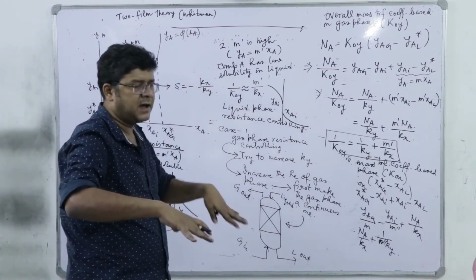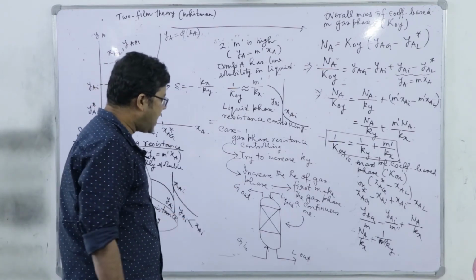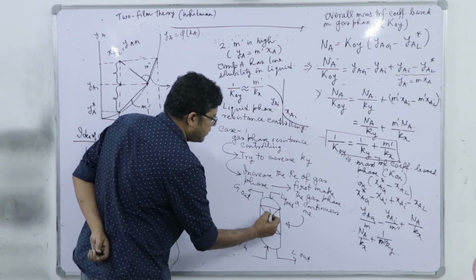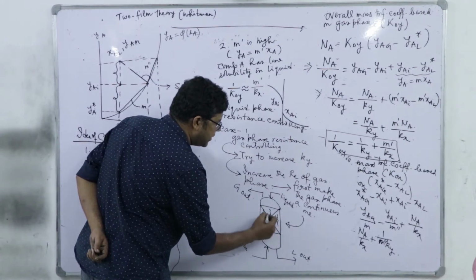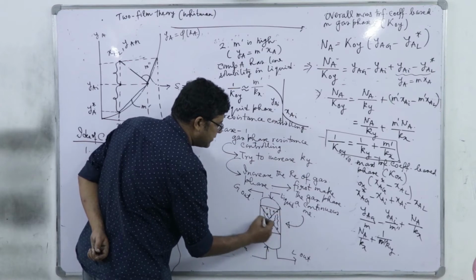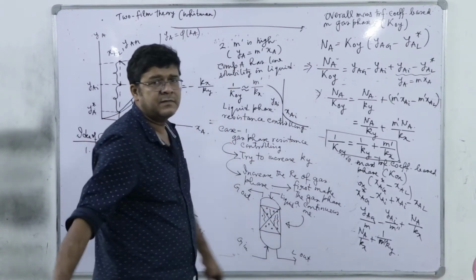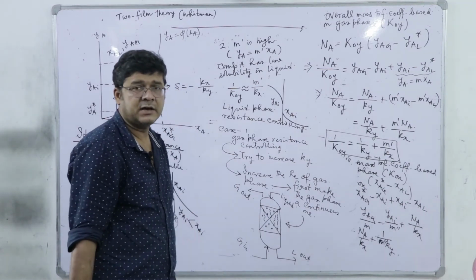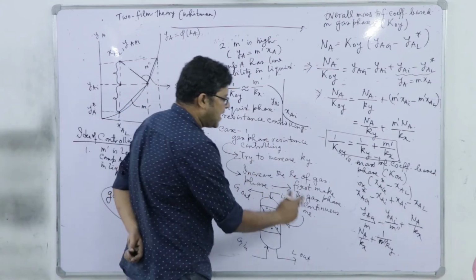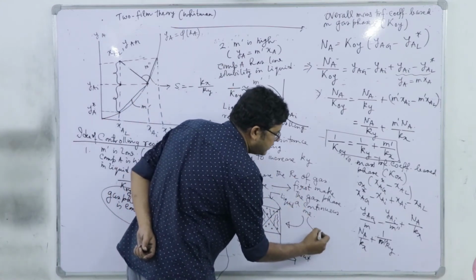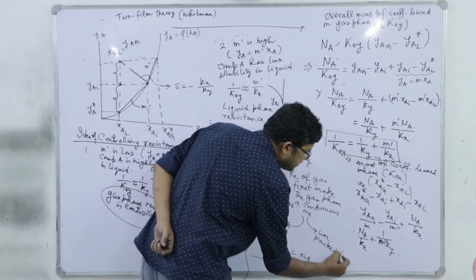Now, whenever we are charging the liquid in this packed bed, so definitely the liquid will be forming the rivulets or dispersed drops, it will wet the surface and all, and through which the gas will be flowing upward, right. So gas phase is continuous. So if I have to make the gas phase continuous, so we have to use packed towers.